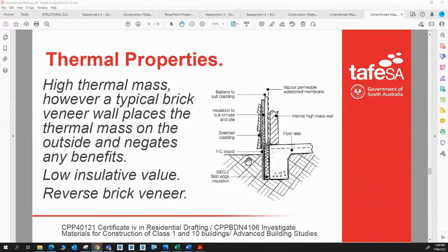So a lot of our construction, from the 1950s through to the mid 70s, was of cavity brick construction. There are several reasons we don't have that type of construction these days, well, because it's thoroughly expensive. There's a great deal of expense in the actual brickwork on a building. As soon as you go doubling that up, you've got a lot more weight to transfer to your footings, a lot more cost of buying those bricks and a lot more cost of laying those bricks. But then also in that type of construction, you don't have an insulative layer within your building unless you provide a 50 mil rigid insulation board within that cavity.